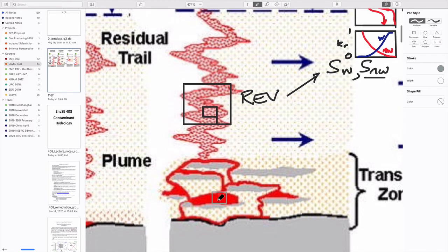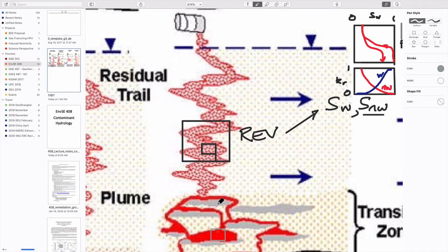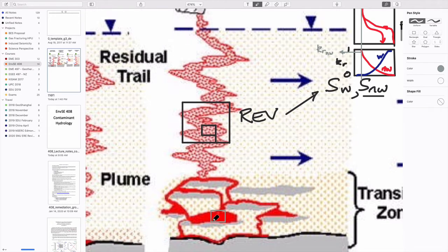then we know that the saturation of this is quite high. And in that particular case, if the saturation of the non-wetting fluid is quite high, then we'd be at this side of our figure. And in other words, quite rationally, if we looked at the relative permeability of the non-wetting fluid, it's almost 1. And so you could rationalize that if you try and suck this out, it will move because it's a continuous phase. There's not much water. It's all oil,